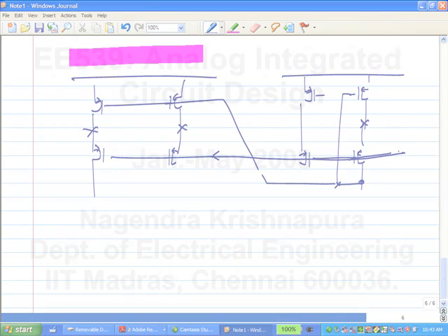Then you will have to further compensate it. Yeah, that's correct, that's true. Sometimes that's a trade-off also. Just to make the common mode feedback loop stable, you will end up adding some load capacitance to the differential path.